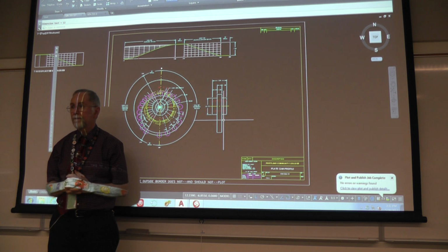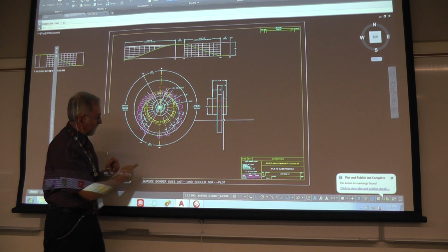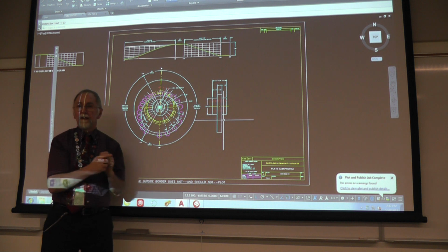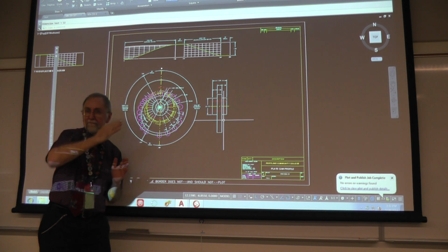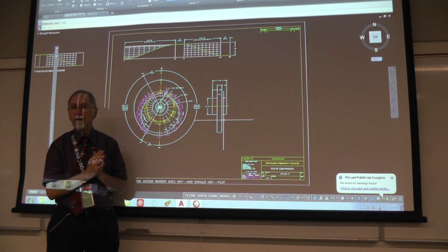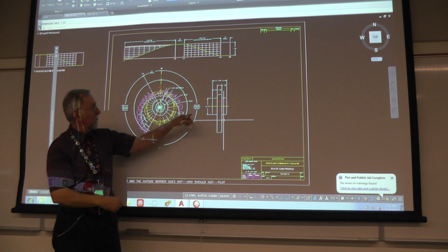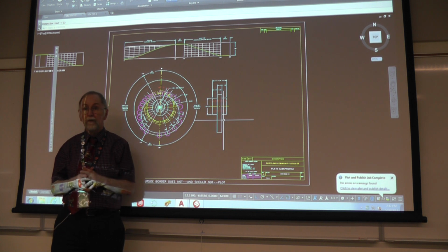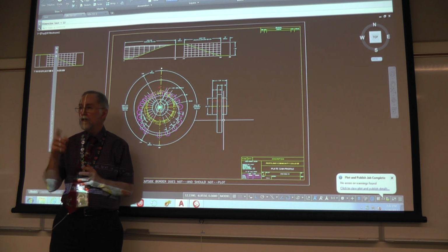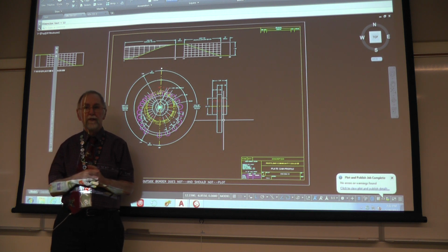Here's the trick. Take this one and rotate it 0.25 degrees or something like that. Cock it over just a little bit. You put it in here, and if you have whole numbers in your dimensioning style, it will read that it's 180 degrees. Okay. And then you can modify the text.